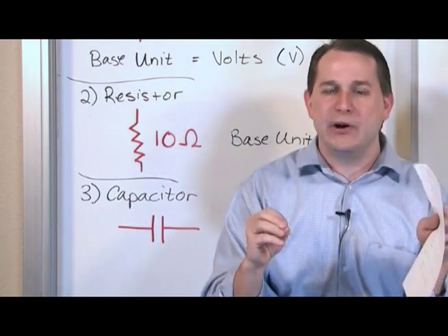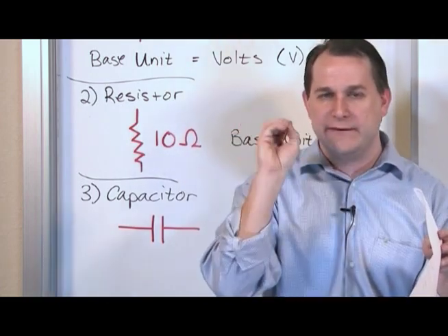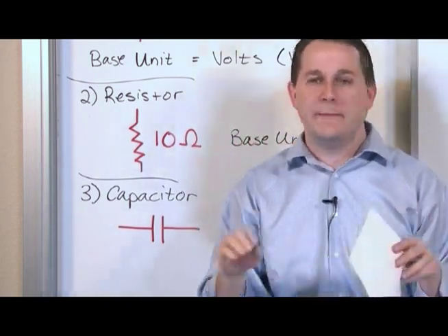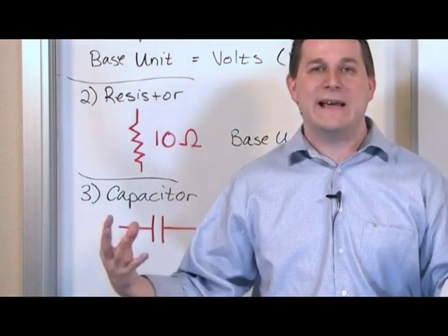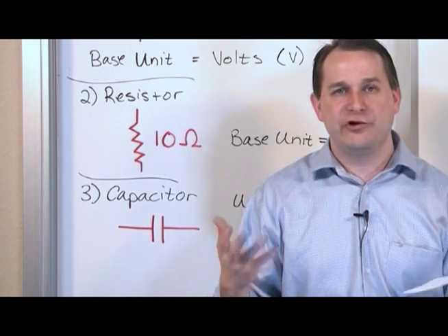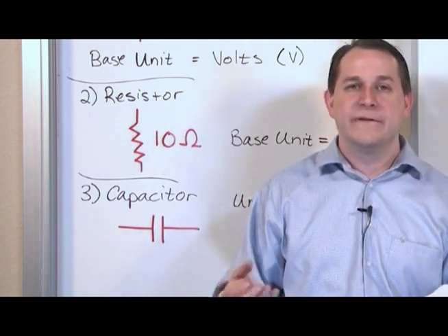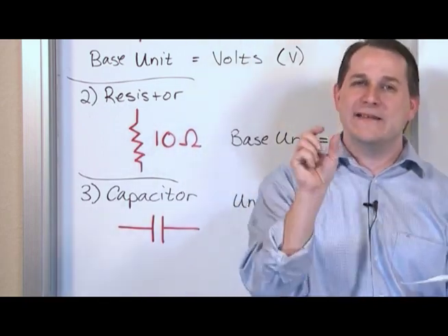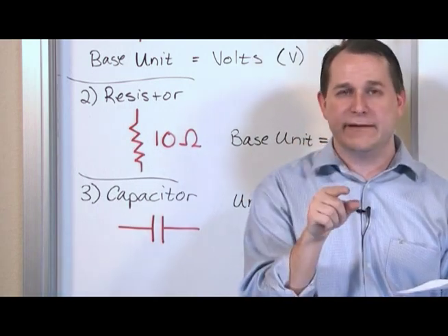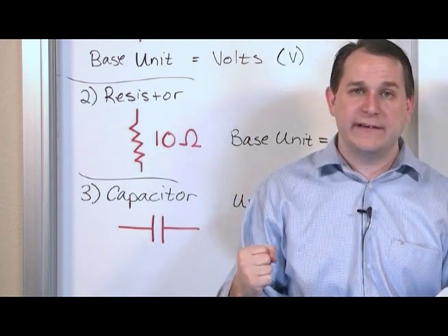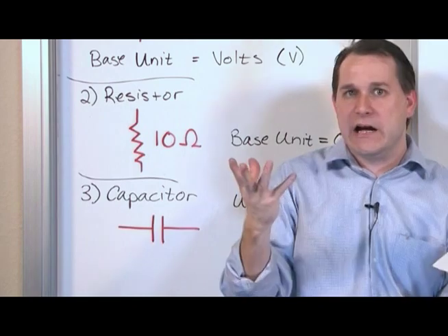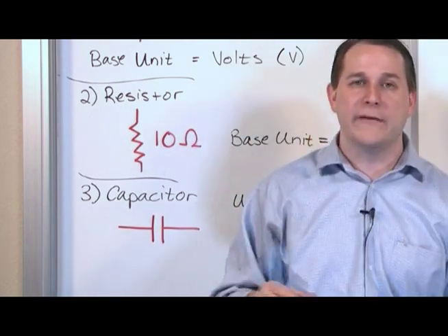And then notice on your camera, it takes a few seconds for that light to come on to tell you, all right, ready to go with the flash. That light takes time to charge up because these capacitors take time to actually accumulate this charge. The reason that you have to accumulate that much charge in a capacitor bank to fire a flash is because that flash bulb is actually a little bit of gas inside of a bulb, basically, and it takes a lot of electricity to jump in there and cause that gas to ionize, for the electrons to jump around and release all that white light.